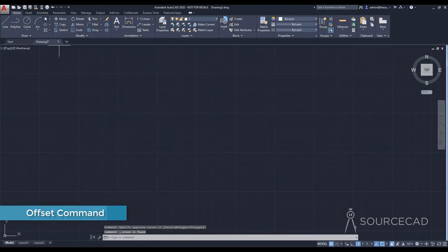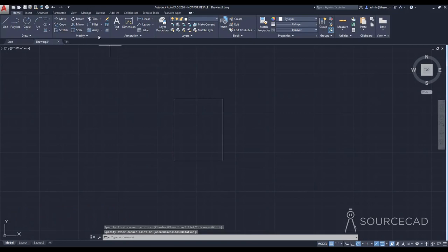So I'll go to rectangle and I'll add a fillet of radius 10 on this corner and I'll press enter. Pressing enter will just repeat your last command. And I'll select this one. Okay, there we have it. Now I'll go to offset and the offset tool will make another copy of your object which is geometrically similar but at a certain distance. So now I'll type in an offset distance of, let's say, 2 unit. I'll press enter. Now I'll select this boundary and I'll move it outwards. So if I click inside, it will make an offset copy just inside.